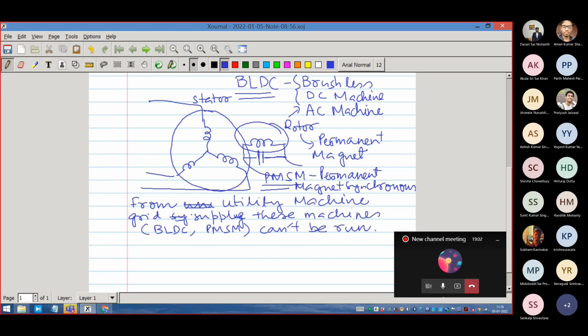In fact, you know the induction machine rotor. I remind you, there are two kinds of rotors. One is called squirrel cage machine, because the rotor takes the structure of squirrel cage conductors, and that is short circuited.